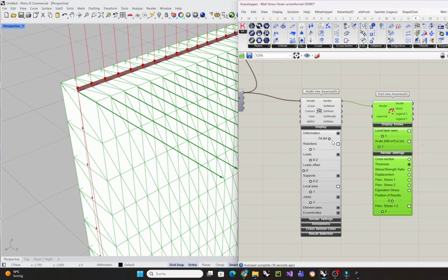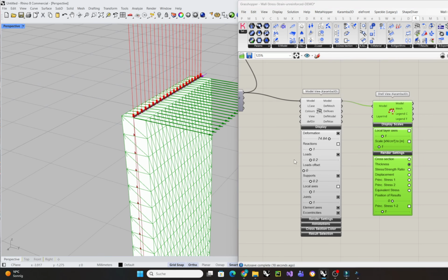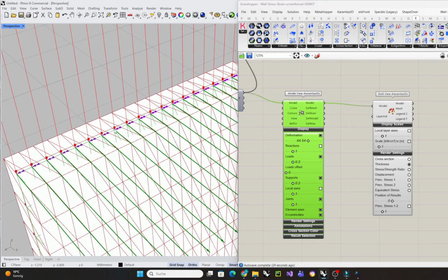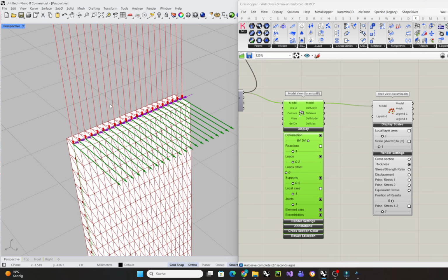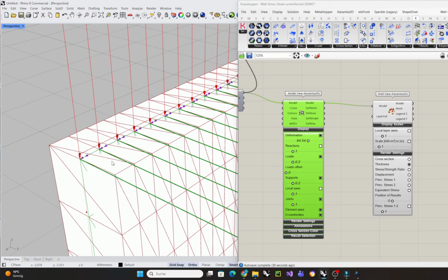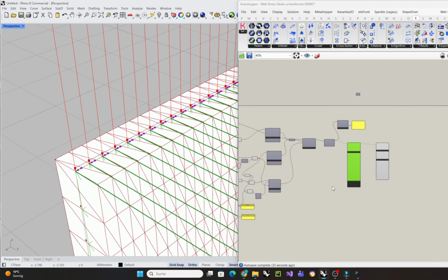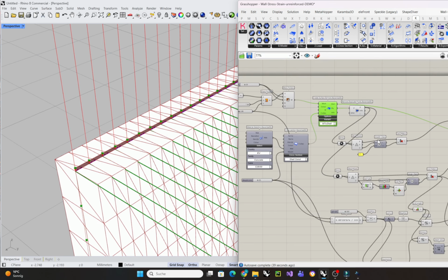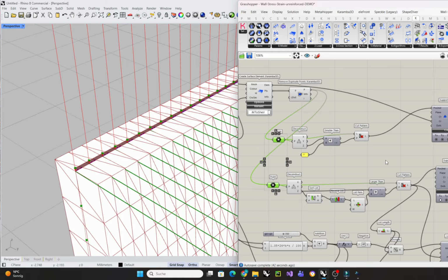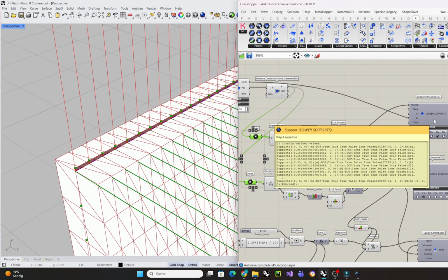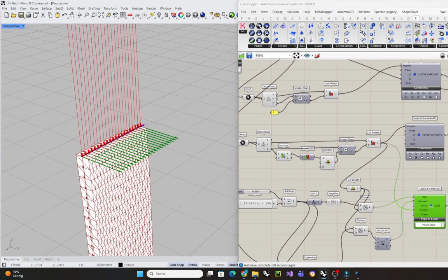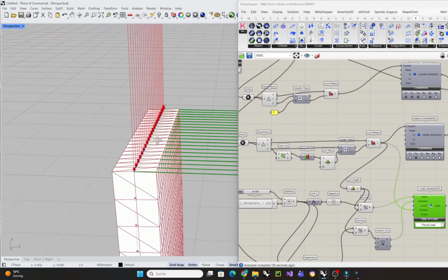Okay, I see the deformation and slight bending. I can see the moment vectors in each point and the vertical load in each node, and also that I've taken these points from the element component, and these same points are extracted to apply the supports and the load. So this is very important, that the points are part of the mesh. This is my side fixing of the wall.